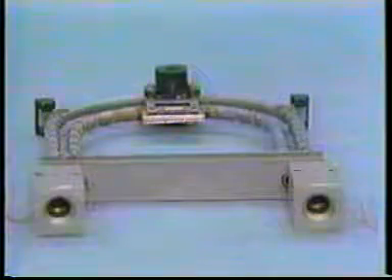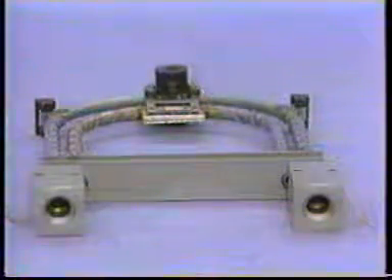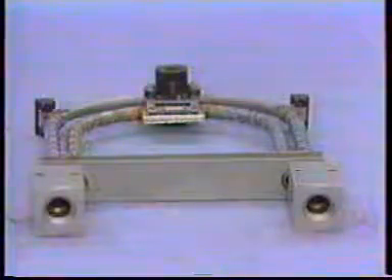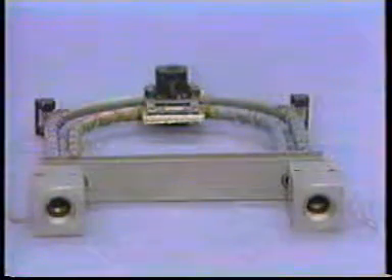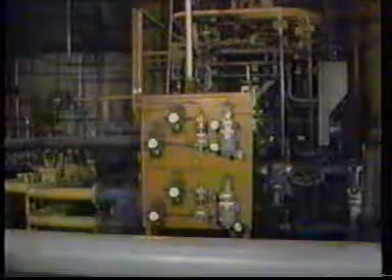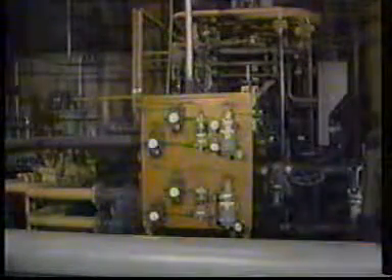Like specific gravity, the Reynolds number is a dimensionless unit and is not absolute for a given liquid substance, but varies with the conditions of flow. As you'll see when we look at specific methods of flow measurement, the Reynolds number is often a significant factor in how well a device will perform and the applications for which it is suitable. You'll find more information on Reynolds numbers in your text.